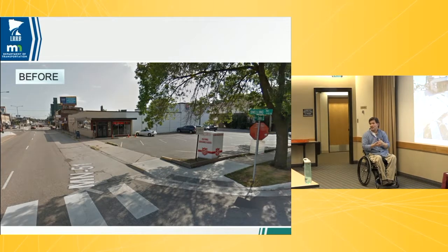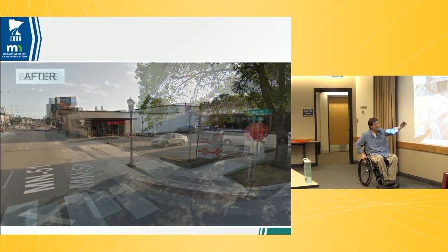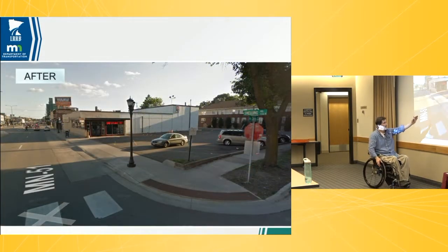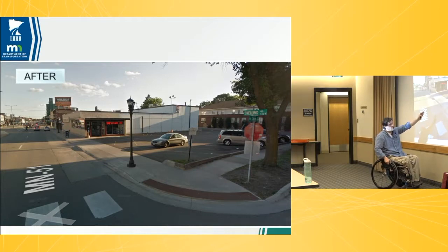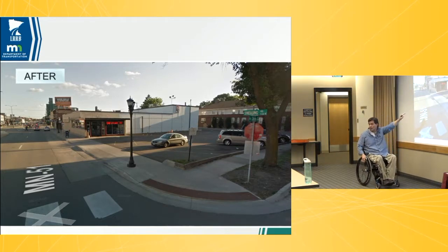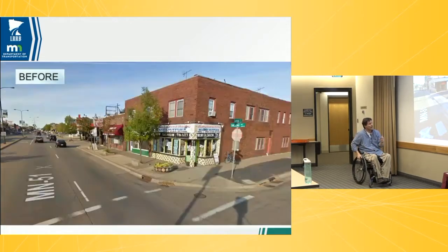But the city actually wanted to do some pedestrian scale lighting, so they wanted to move this curb line out to allow room for that lighting. That allowed us to put an apron in the new boulevard area, have our PAR with just a 2-foot tie-in to the right-of-way. So again, we looked inward so we wouldn't have those off right-of-way impacts, and a really good solution here within our existing right-of-way.